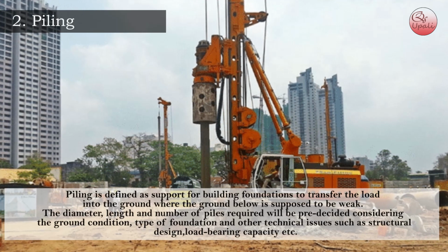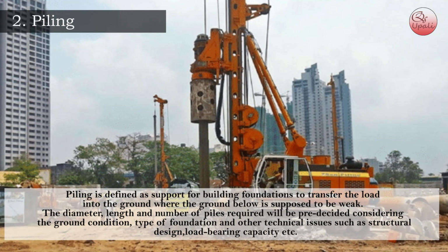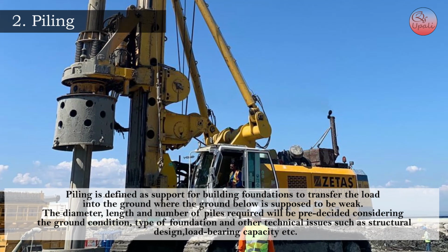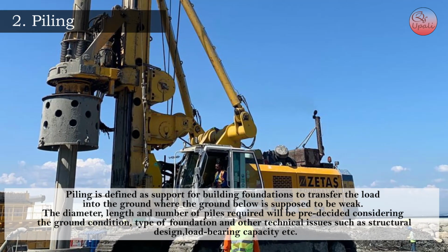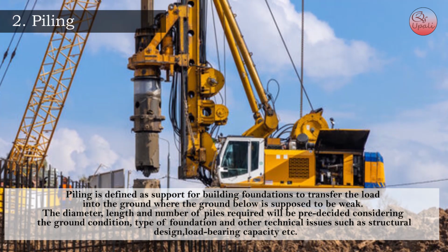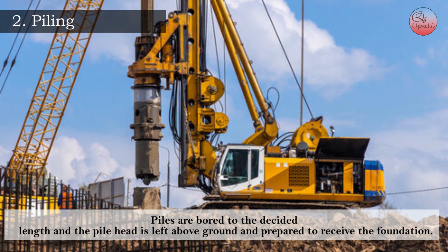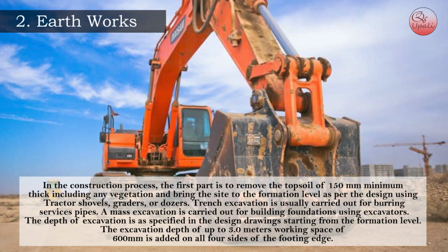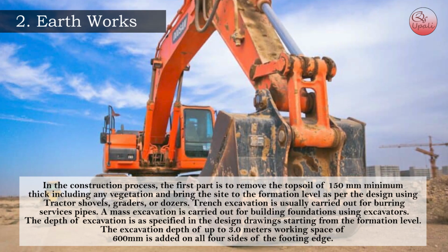Number 3. Piling. Piling is defined as support for building foundations to transfer the load into the ground, where the ground below is supposed to be weak. The diameter, length and number of piles required will be pre-decided considering the ground condition, type of foundation and other technical issues such as structural design, load bearing capacity, etc. Piles are brought to the decided length and the pile's head is left above ground and prepared to receive the foundation.